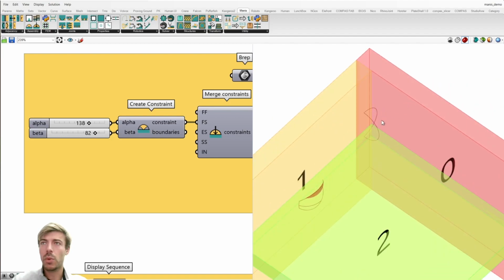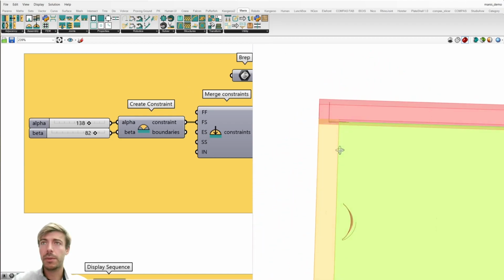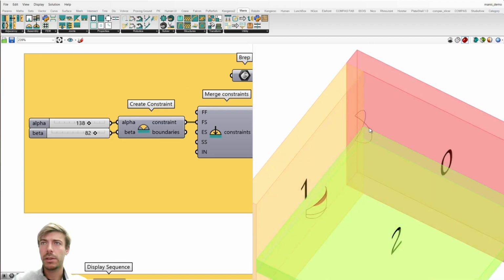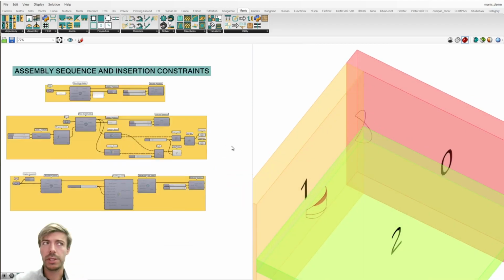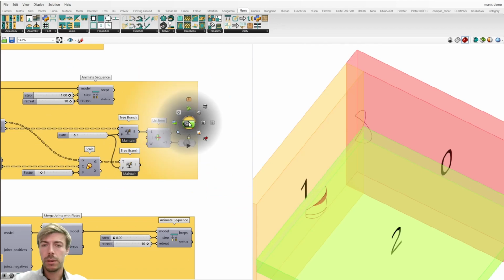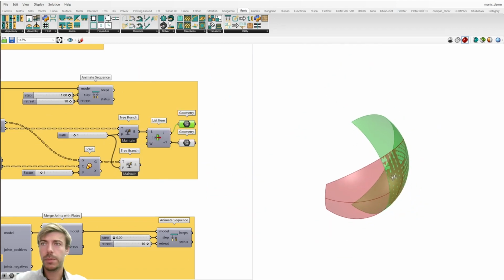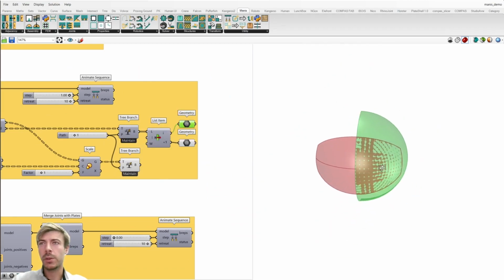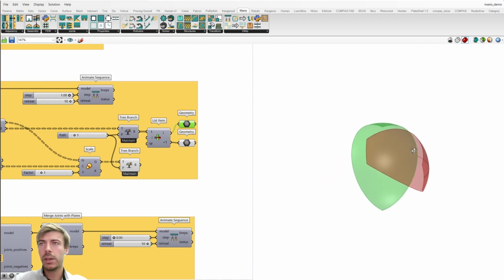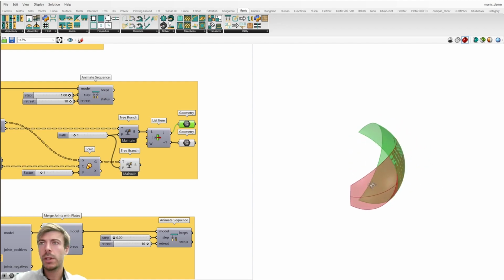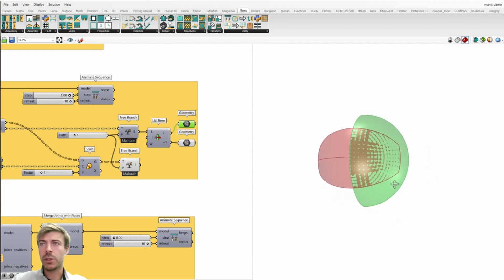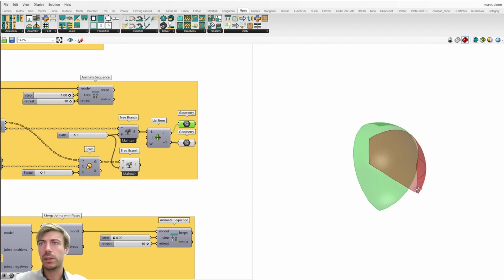And you see that for edgewise connections, here we left it as default. And by default, we have a quarter of a sphere that you don't see really well with that display. So let's zoom maybe on the grouped output. And so here we have the two pieces of sphere that represent the custom insertion domain for the true tenon joint and the default insertion domain for an edgewise connection like the Negiri Arigata joint.